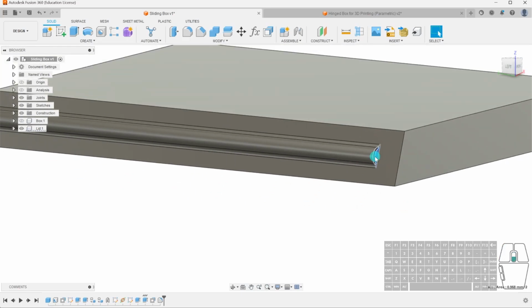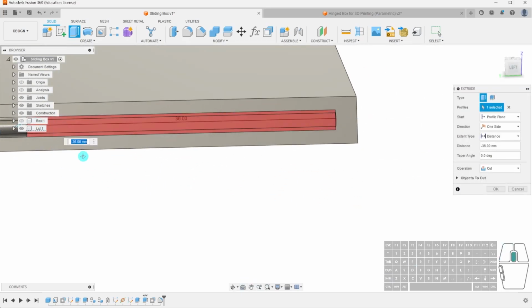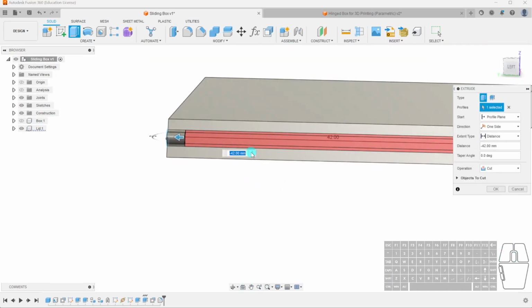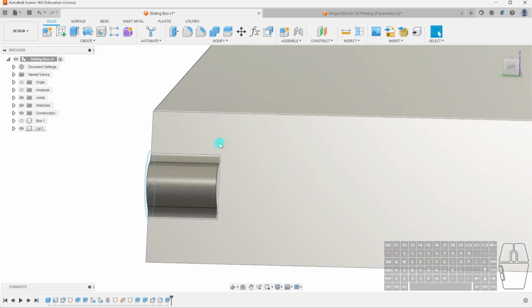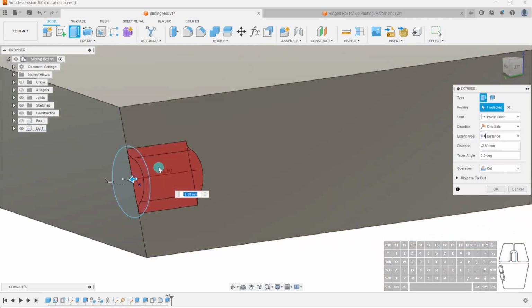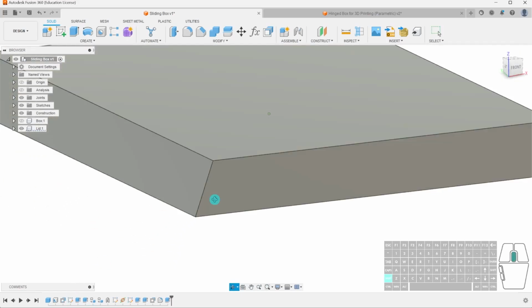So in this case, what I can do is just very simply move this back, and let's just say I move it to somewhere here. Okay, and if I check, I can see that the distance of this little nub is 2.5 millimeters. I can always change it by going back to my extrude and increasing the length of my extrude.